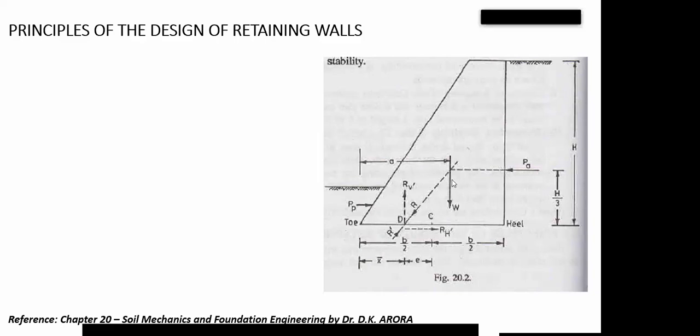Now, your resultant is coming vertically downward. If you remember your Cartesian coordinates and normal resolution of forces, I know some people must have seen it. As this is coming like this, and I have my weight, I know my resultant will be coming like this. Now, my resultant will be acting at this particular point on the base of my retaining wall. That particular point, I call it point B. Also, the resultant effect of the applied forces due to the lateral earth pressure and the vertical weight is acting on this point. For this thing to actually stay, there must be a counteracting what?